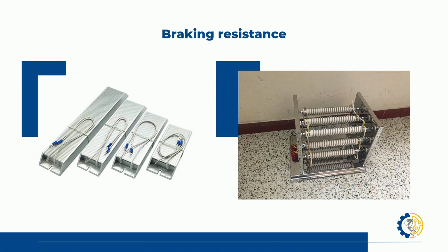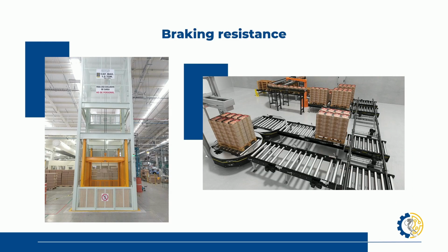What do you guys think? Do all applications need brake resistance? Not all of them. The manual says all of them. But we should be able to know the difference if we need it or not, which is the same thing that I had previously told you. Okay? Because if this is a conveyor, do you think we're going to need the brake resistance? Well, not really. So you basically need to analyze if this is needed or not.